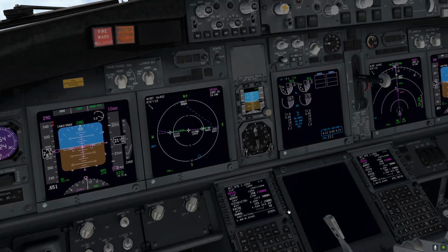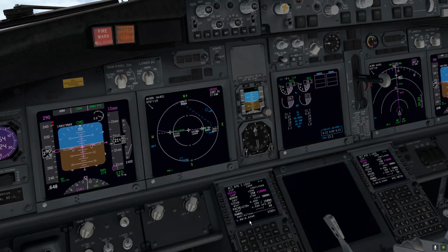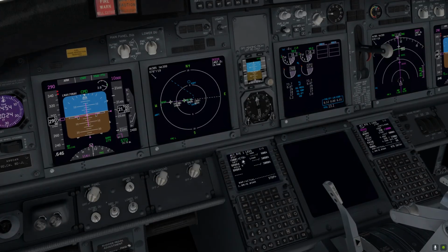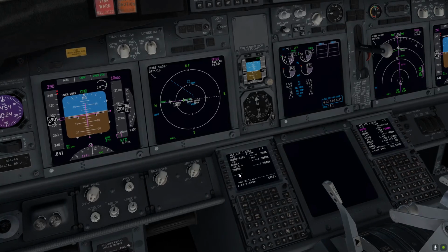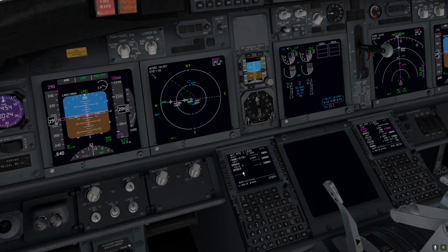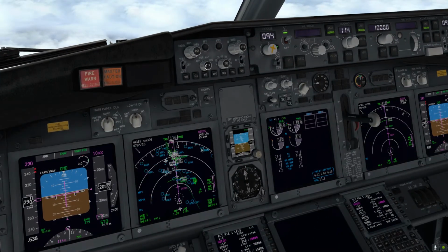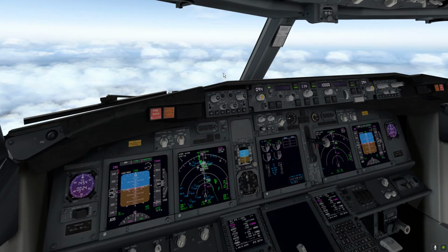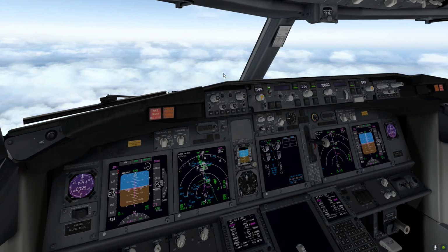Vikov, and then the RNAV approach, and for this missed approach climb 800 feet. Let's cross check it as well. Climb 800 feet and then turn left, climbing 3000 direct to Bravia, Bra, and hold. That's in the box correctly as it should be. I think we might enter back into the cloud shortly.